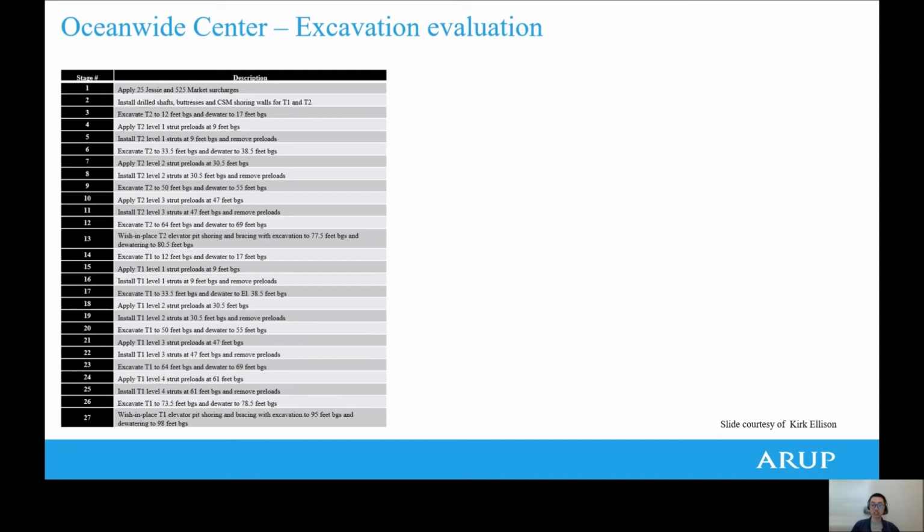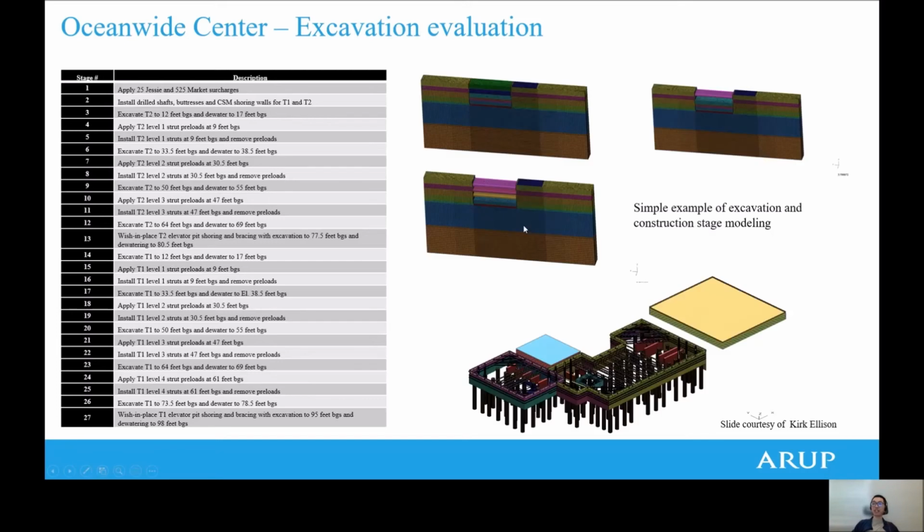And this can be achieved using LS-DYNA construction stage analysis, which is a very special kind of analysis case. You can see on the right top here a very simple example where the soil is excavated and the braces are added. So we use this concept to do the same thing for the 3D model, applying this construction stage analysis to mimic all the sequences listed in the real 3D model built.